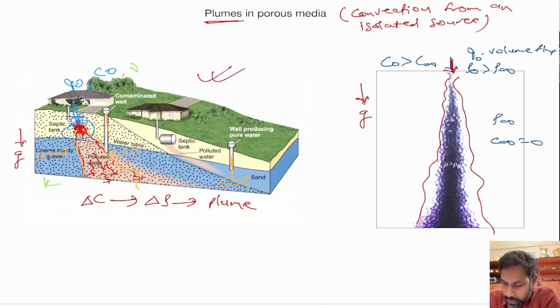Okay, so with this, we conclude plumes in porous media, as well as overall flow in porous media, where we have discussed both the flow part as well as the mixing part. In this particular topic, what we did today is plumes in porous media, which gets generated because of some continuous release of denser fluid. Okay, and by using this simple mathematical model, you can very easily predict the amount of contamination, and also the location of the contamination, etc.